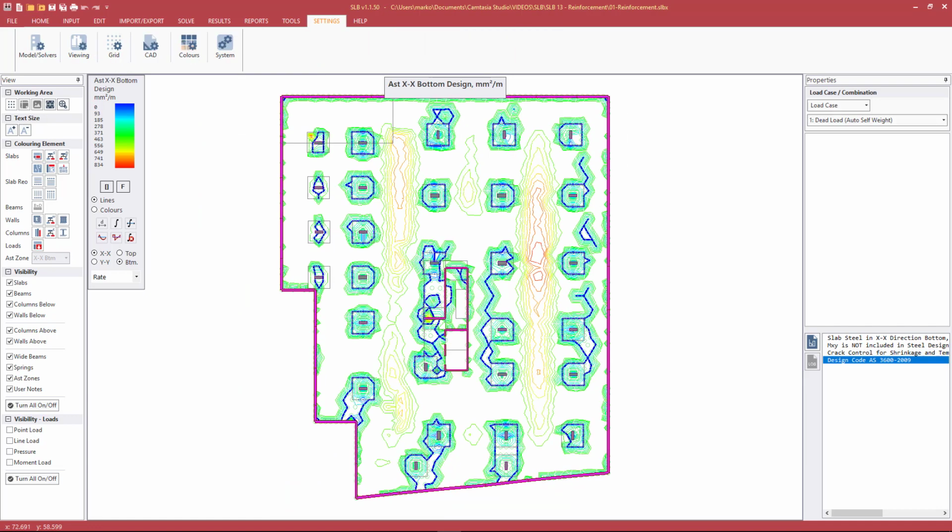To determine the user-defined reinforcement, we'll look at the reinforcement results. We'll pick two sets of reinforcement results that we'll input into the interior parts of the slab and then into the drop panels. So we'll put a constant grid of reinforcement that covers the majority of the reinforcement requirements. Then we'll design these spans that need additional steel just to have extra steel locally in these areas.